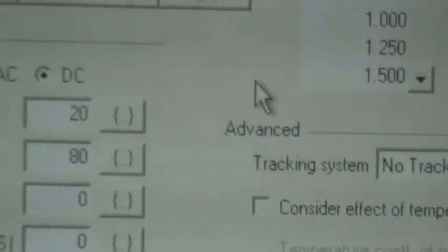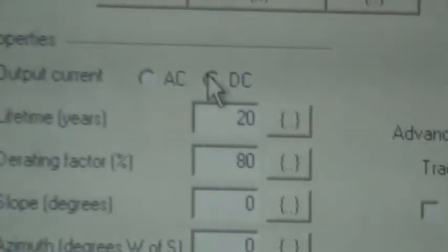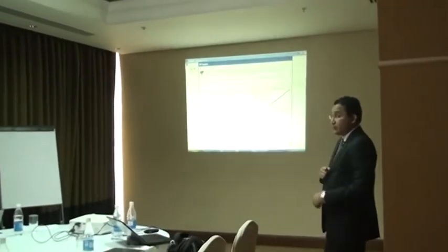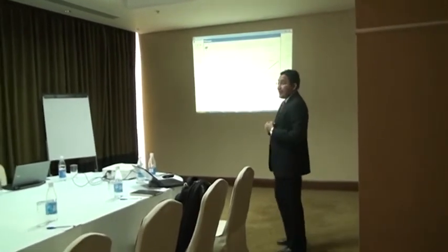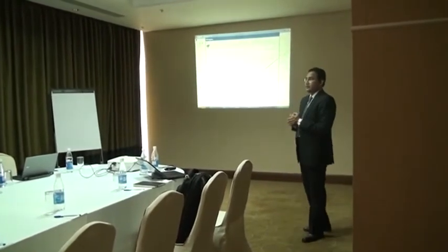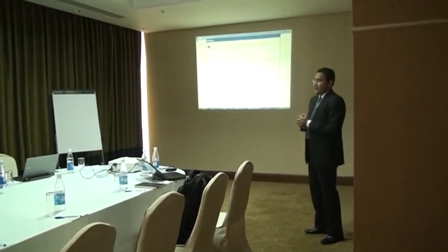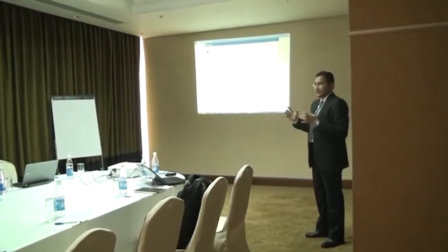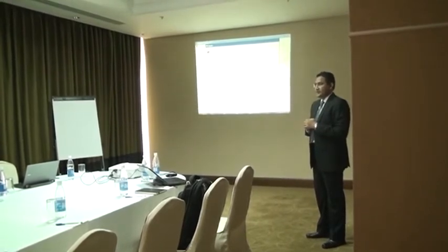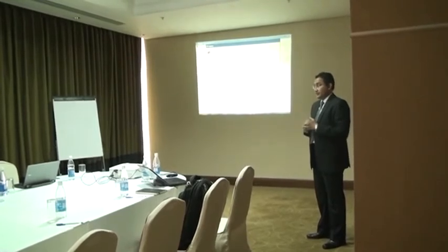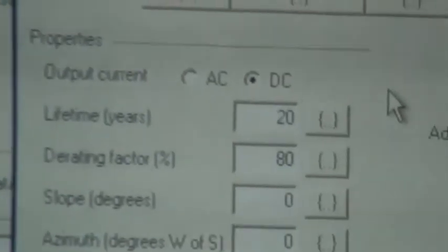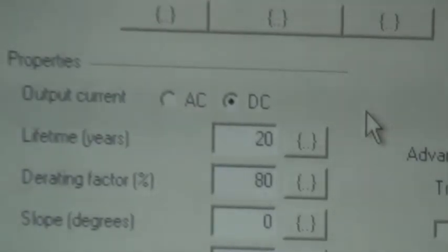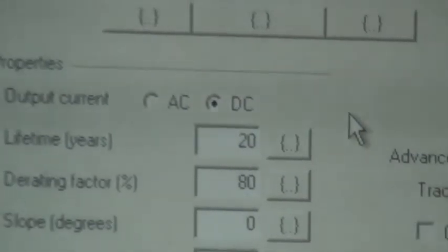Eventually it's a DC. Lifetime. Now it's a set lifetime of 20 years, the default value. You can reduce it to 10 years. We never recommend considering 20 years. I mean, probably manufacturers or vendors will argue with me, but we have done extensive work to understand different solutions. We have been dealing with multiple manufacturers, and we have done a lot of joint work with grid power manufacturers, especially with PV-based mainstream megawatt level. And we realized that the efficiency degradation is not bad actually. It's about 1% per year.